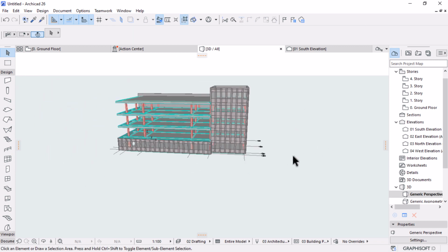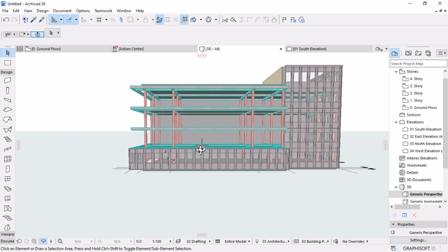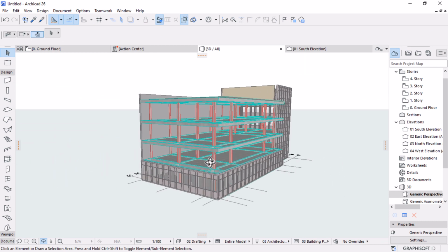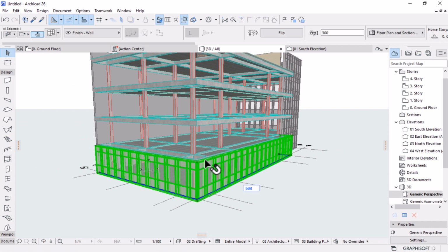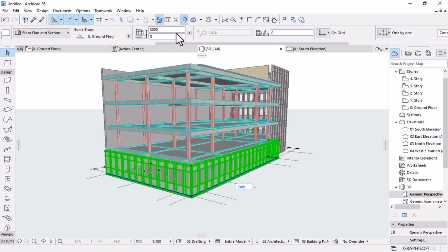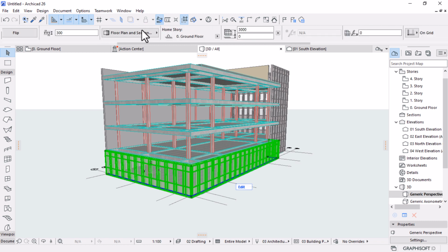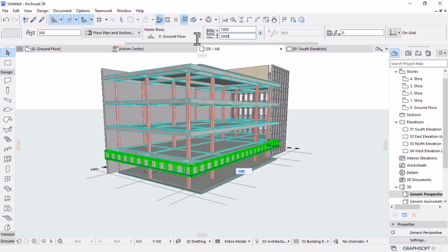Something like this. Okay, don't worry for now with these settings of the curtain wall. We'll make it look way much better. And then for here, I would select this. This should go all the way. It will start around 2 meter height. So what I need to do is scroll down here under the info box, set this to be 2 meters, something like that.